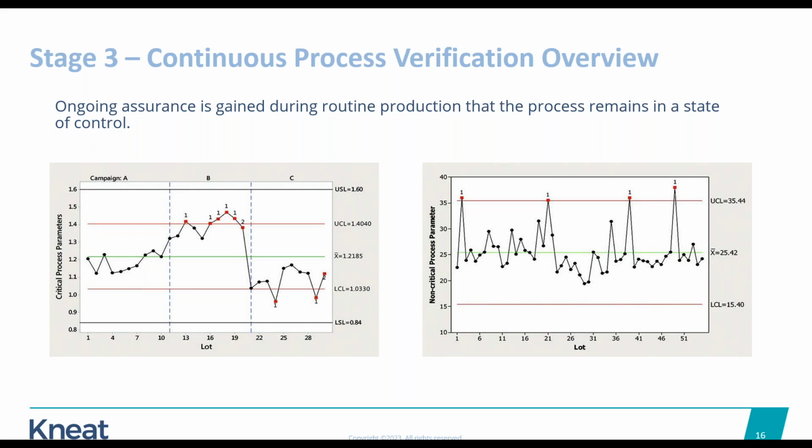And for example, if we go back to our hold times that we talked about, if there's one hold time during the process that you keep exceeding time and time again and deviations keep needing to be opened, you could go back to stage 2, do a couple hold studies there, and then validate that new hold time and then minimize the deviations in the future. So you have that flexibility here to improve your process.